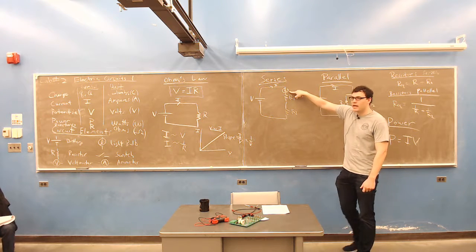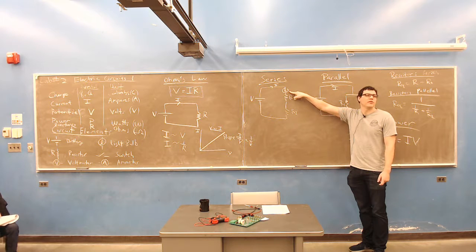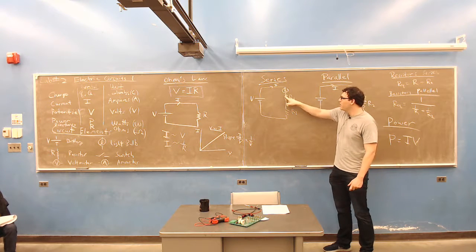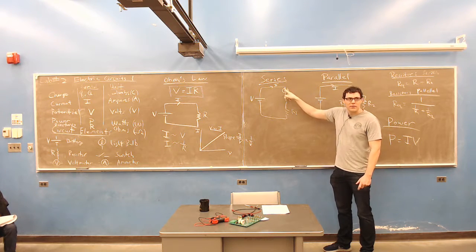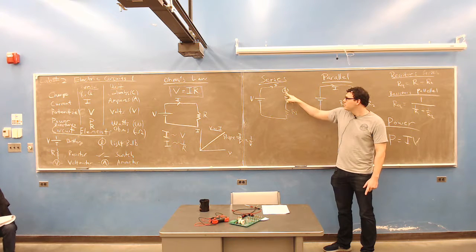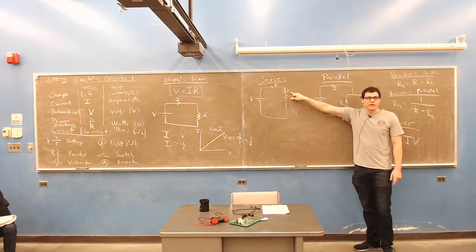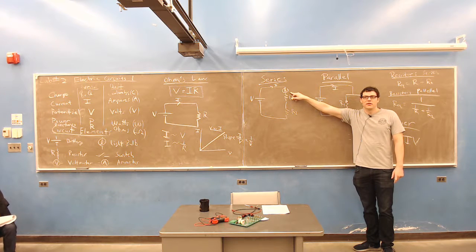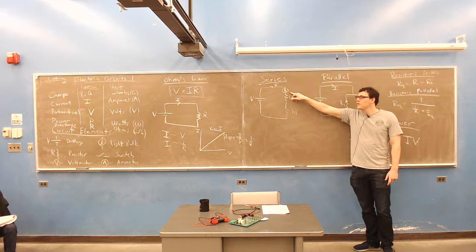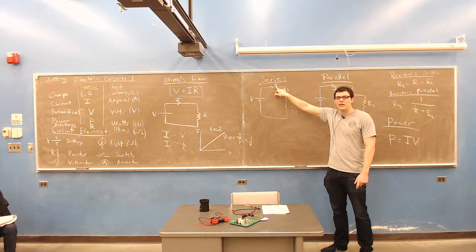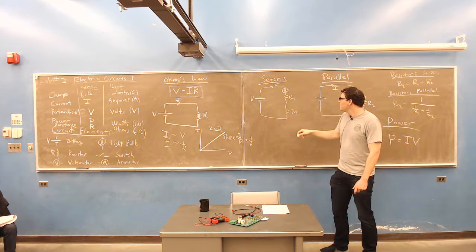The way you use the ammeter is you put it into the circuit. So you literally have to break off the wire and put it in and complete the circuit. So this guy is in the circuit, this ammeter. What's this ammeter going to read? Yeah, the current which happens to be I. All right.